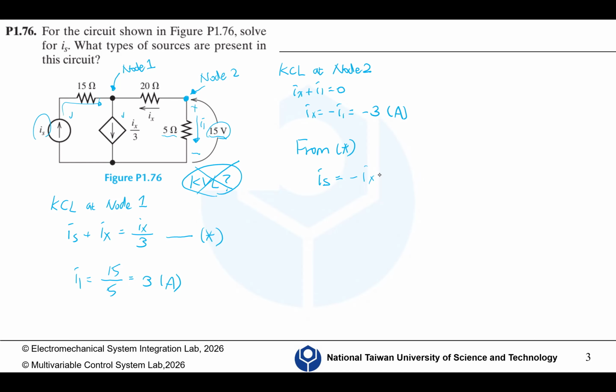Given the positive and negative directions of I3, the voltage here should be 10 I3. So I immediately know that Vx equals 10 I3. So I can replace Vx by 10 I3, keep 3 unknown variables, not 4, and we just need to list 3 equations.